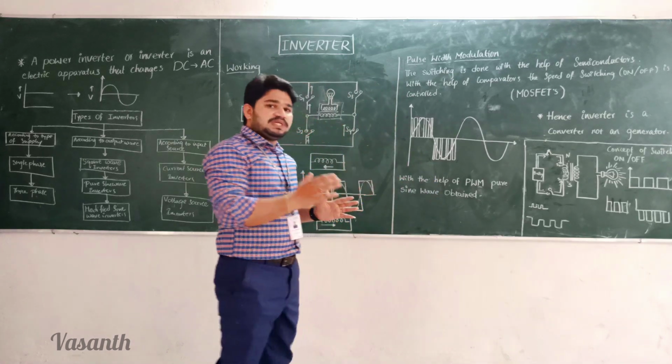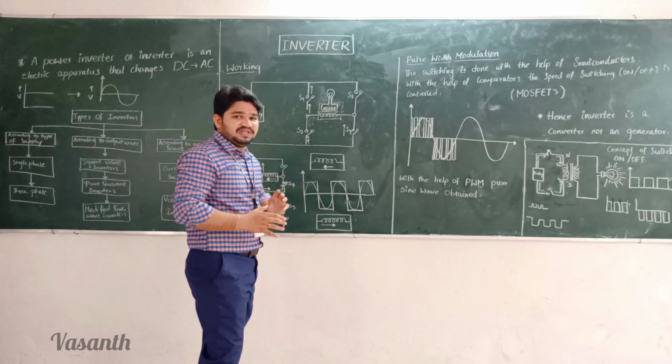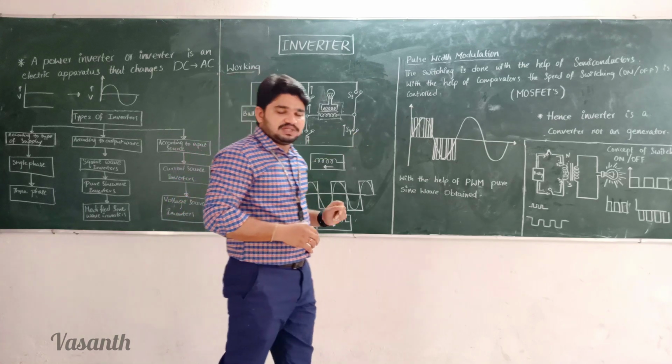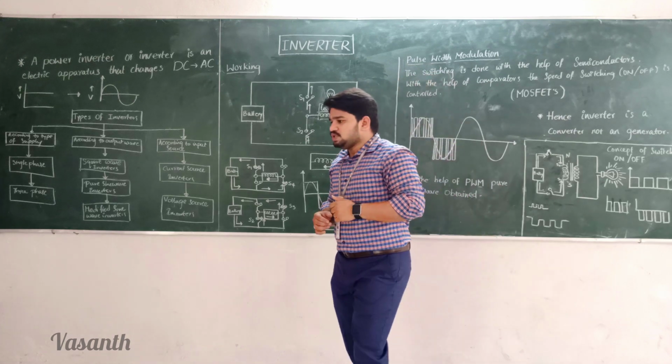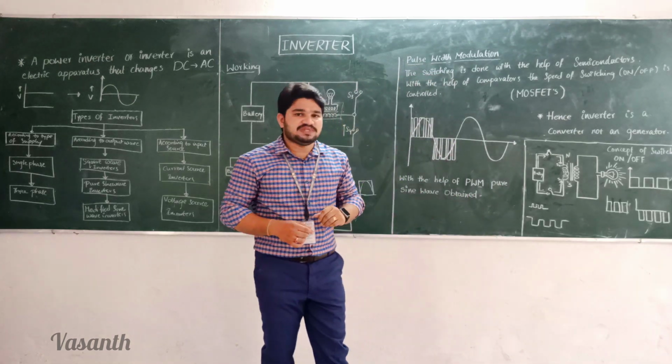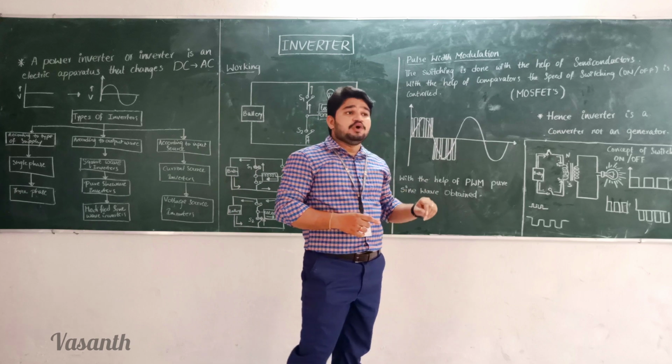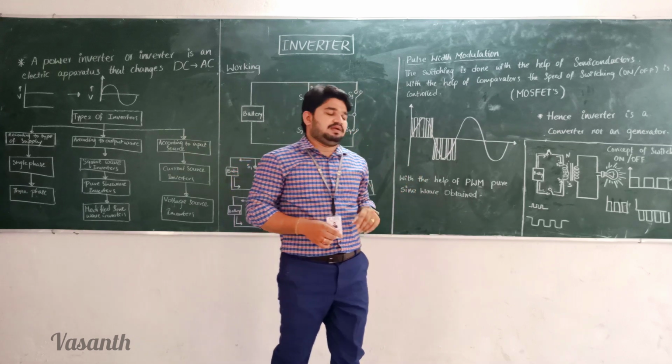So this concept is used in inverters. This on-off switching should be done depending upon the frequency we need. So if we need 60 hertz of frequency, we have to switch on and off 120 times in a second.